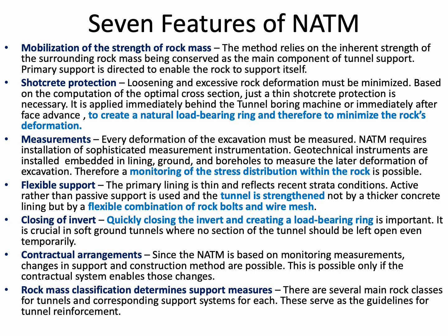Closing of invert. Quickly closing the invert and creating a load bearing ring is important. Contractual arrangements need to be made for taking into consideration all these flexibilities of changing the designs of the supports as required by the ground conditions.